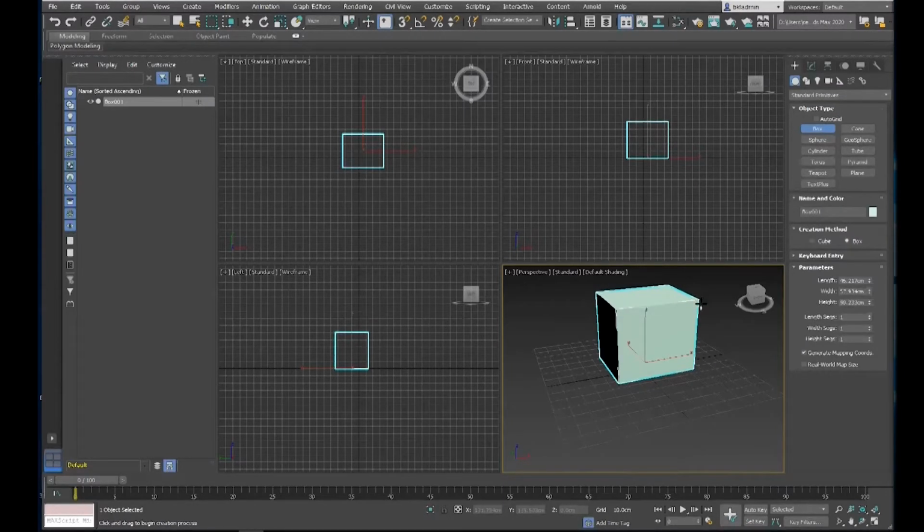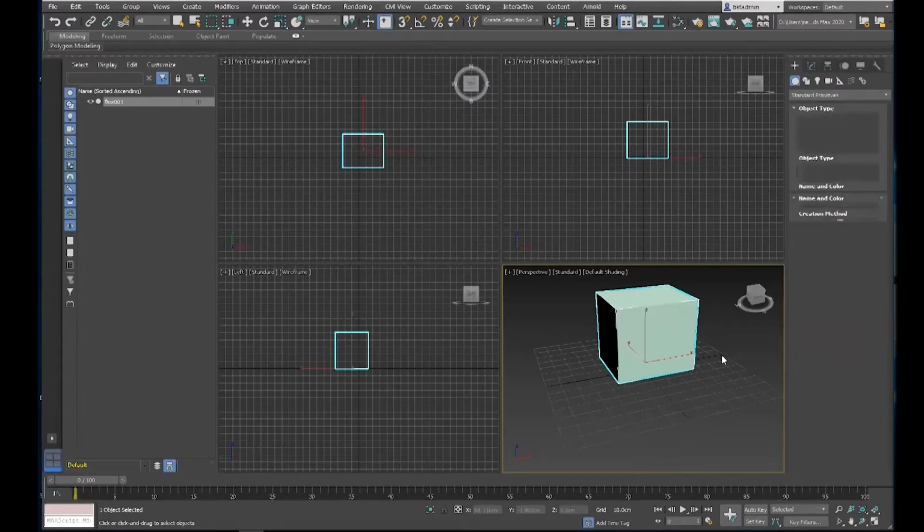And if I'm satisfied again, I'm clicking and I'm complete with the box. But be careful, we are not ready yet because we are still in the box command. So box command is still active. What should I do? If you remember in the previous lessons, right click is exiting from pending operation. So right click exits from a pending operation.